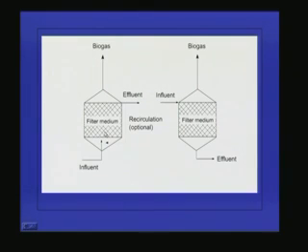This system can take a lot of organic loading, in the range of 10 to 20 kilogram per meter cube, that is the organic loading rate. And one of the problems usually faced in this type of filter is clogging, because with respect to time the biomass concentration or biomass thickness in the filter will be very high, and that will slowly decrease the porosity of the medium, and filter clogging can take place.